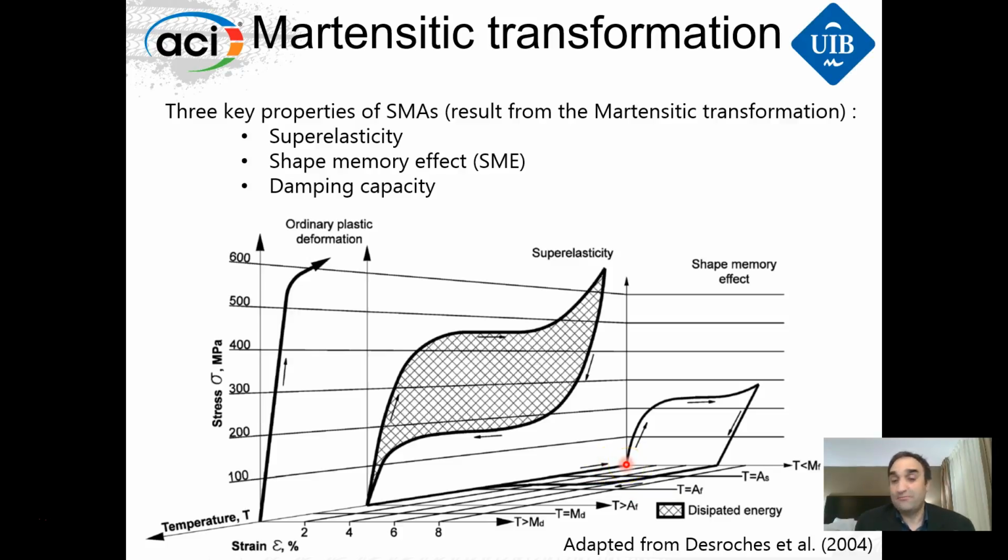We go to the origin, to the beginning of all the process. So this way we are going to be able to pre-strain structures. How? Well, it's very easy. We have the pre-strained material, and then if the material is free, no constraint, we heat it, and we have, you can see here, the recovery of the strains. But if the material is constrained here, then we will generate stresses, and we will talk about recovery stresses.